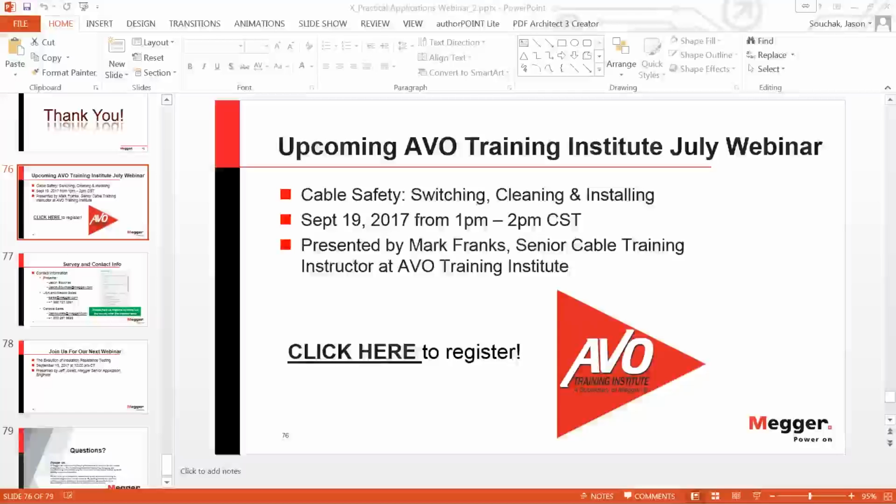Well, the only thing I would say is if you see this on one test, on one phase, to me it would be interesting to see at what voltage level it occurs. Does it seem to be at the higher voltage level or the lower voltage level? And I might just rerun the test on that one phase just to see, is this something that's always there, or was it just a fluke? Because sometimes you get a fluke reading.